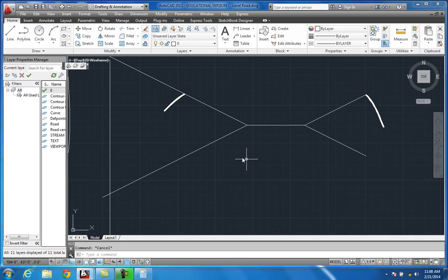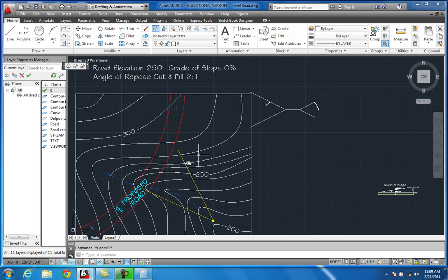The fill angle of repose is just completely opposite of that. Let's say that you maybe had a valley. Well, we've got to build the road up. You don't want to build a road up completely vertical, because if something happened and the guardrail didn't hold and somebody hit the guardrail, you'd come straight over the cliff. If you build it up like this, you won't have the road breaking out or things of that sort. And also, just in case of accidents, you've got a gradual slowdown instead of something just falling completely off the side of the road.